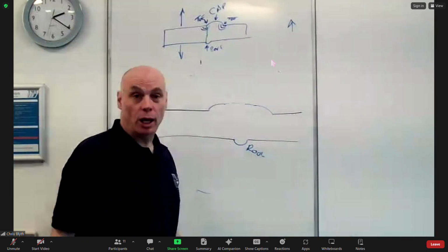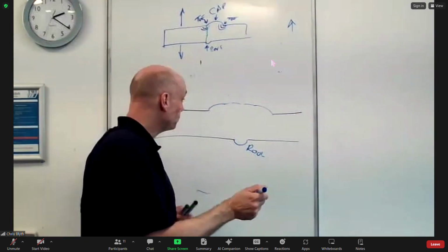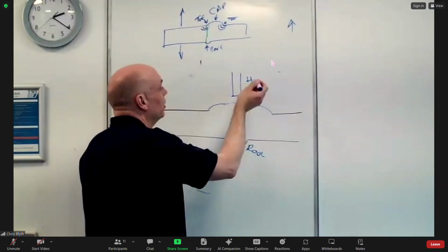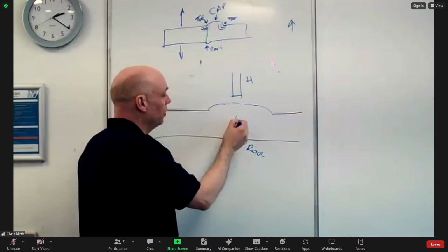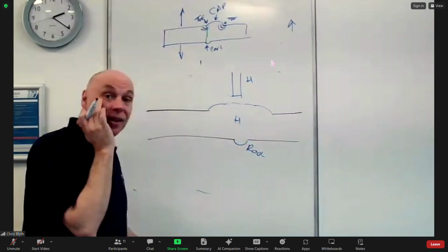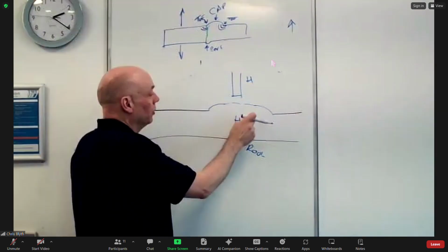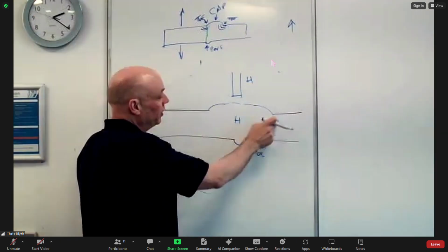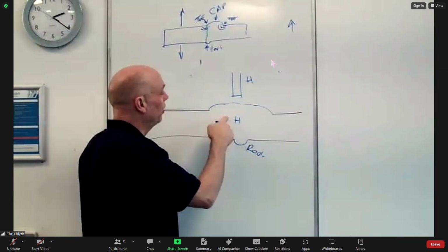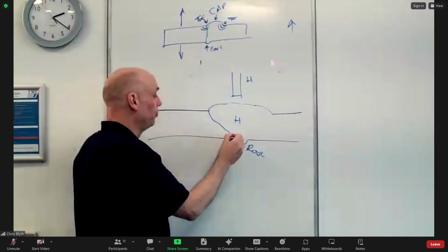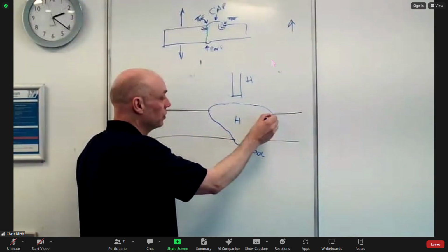Okay. So what can happen when we're welding, okay, is we can introduce hydrogen from the electrode into the weld metal. Okay. And what we've got, for all we said, this is one mass of metal. Where the weld metal, parent metal meet, is fusion boundary.